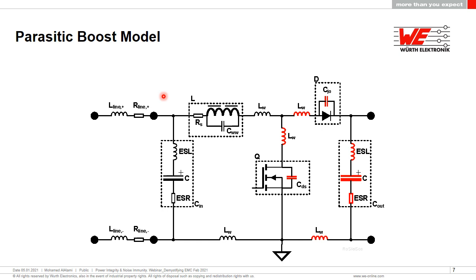Unfortunately, it's the parasitics in that model that result in much higher frequencies, much higher noise, being introduced on those lines, input or output. This is where it is critical for us to try to minimize the impact of these parasitics. On some occasions, you can't do anything about it because this is part and parcel of the actual component being used, but as you will see later on today, there is an opportunity to select a better type of component sometimes, which will give you a lesser parasitic effect.